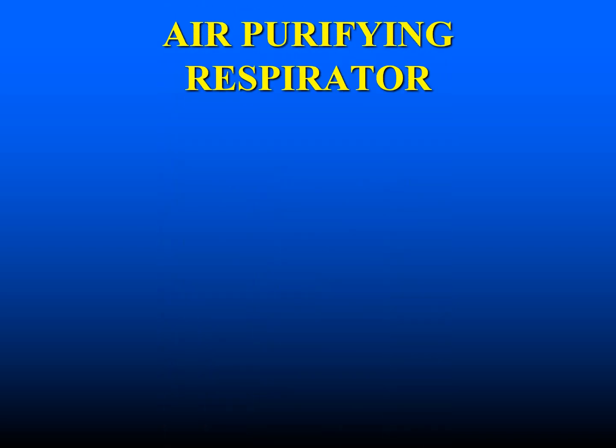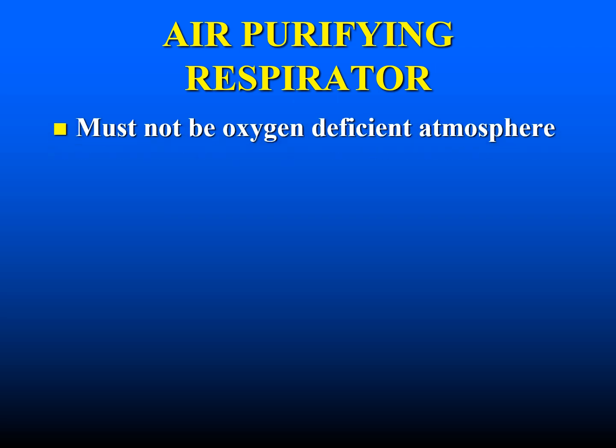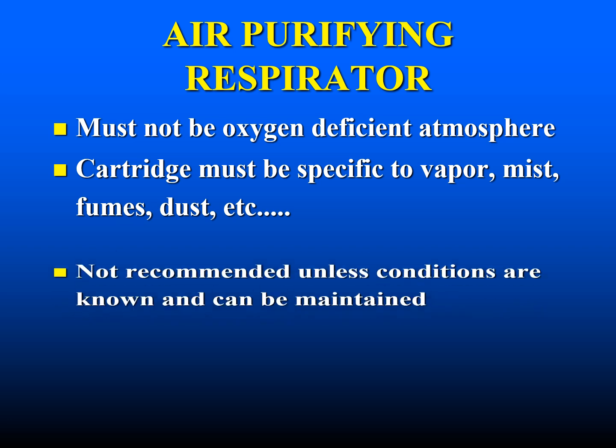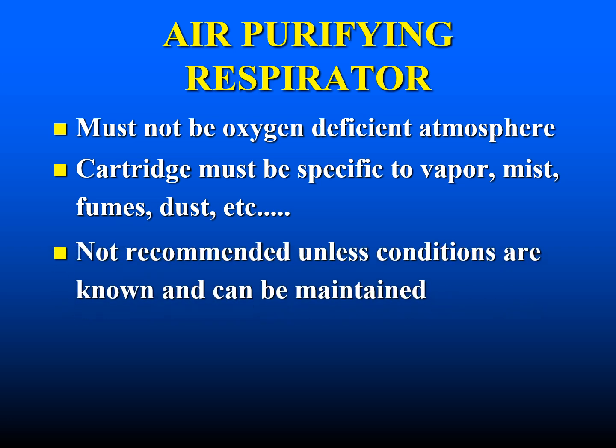Next, I want to talk about the air purifying respirator. We have to make sure that the space we're going to enter is not oxygen deficient. The cartridge must be specific to vapor, mist, fumes, dust, etc. An air purifying respirator is not recommended unless conditions are known and can be maintained.